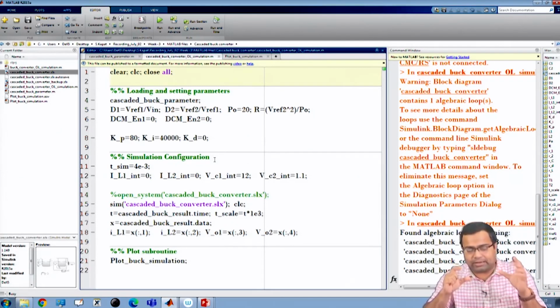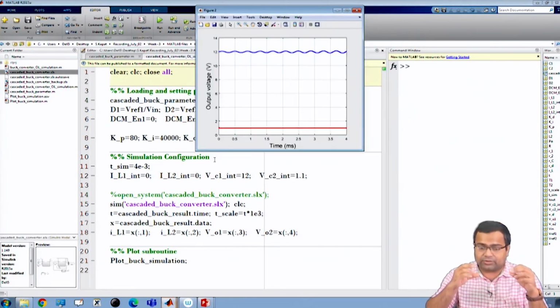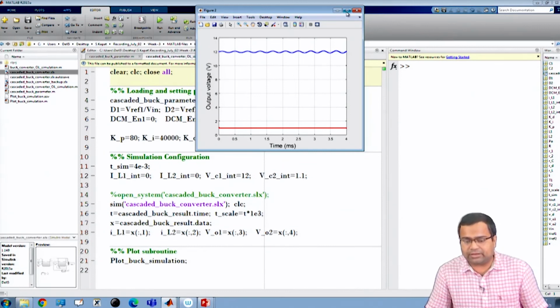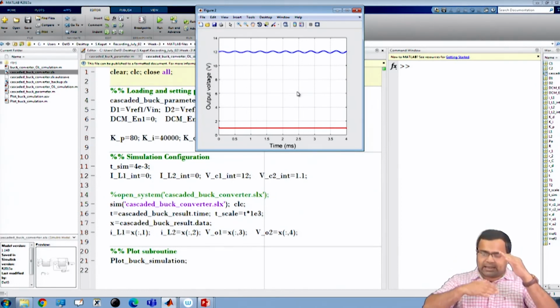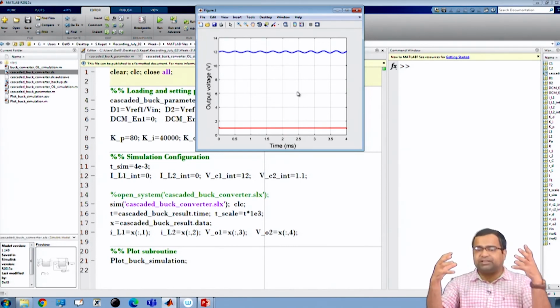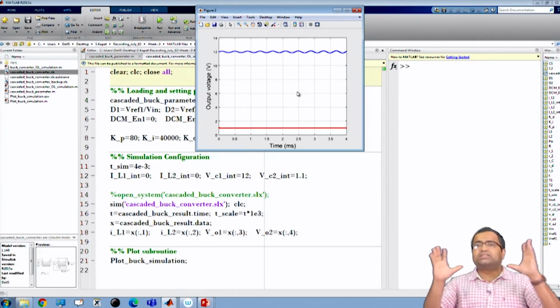This is particularly important because we sometimes need to keep a smaller capacitor in the bus architecture. We will come to the discussion, because this smaller capacitor of intermediate bus architecture can help to quickly change the intermediate bus voltage, which can be used to optimize the performance and the efficiency of the POL converter. This is very useful for the trade off between performance and efficiency in the two stage architecture.